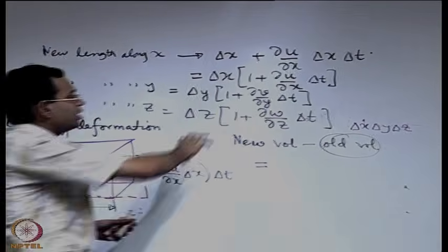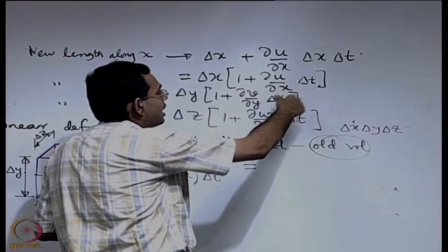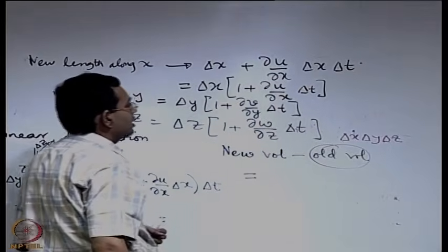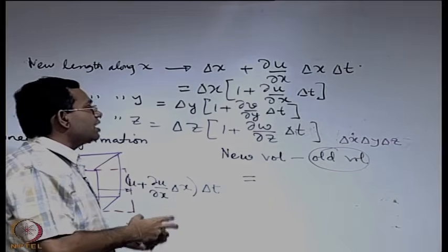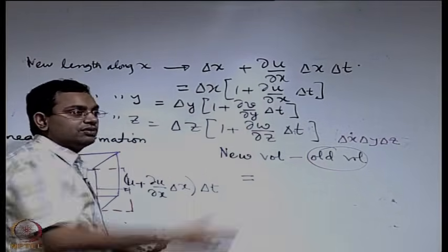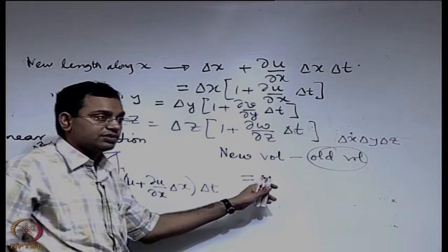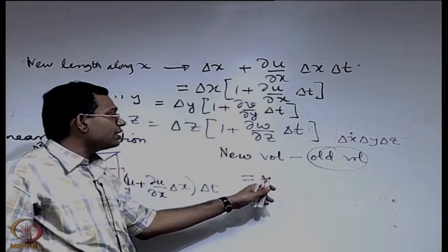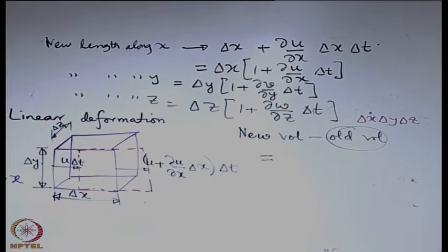Then out of the remaining terms you have to neglect the terms of higher order in delta. So like if you have products like delta t square or delta x into delta t square, that type of term you tend to neglect because those are higher order terms. So retain only the leading order terms, because you have to keep in mind that you are dealing with a situation again as delta x, delta y, delta z, delta t all tending to 0.